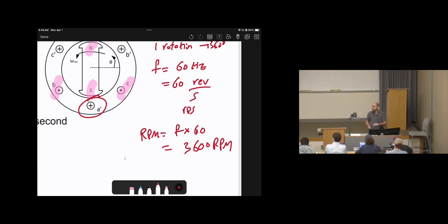That's why we say synchronous is suitable for constant speed, constant frequency. So we need to have a device that works only at that constant speed. Now, sometimes for very big generators, if that generator rotates at 3,600, this is fast speed, maybe there will be vibrations, there will be some losses, or something like that. So it can be unsafe operation. Can we make it slower speed than that? The answer is yes. How? By increasing the number of poles.